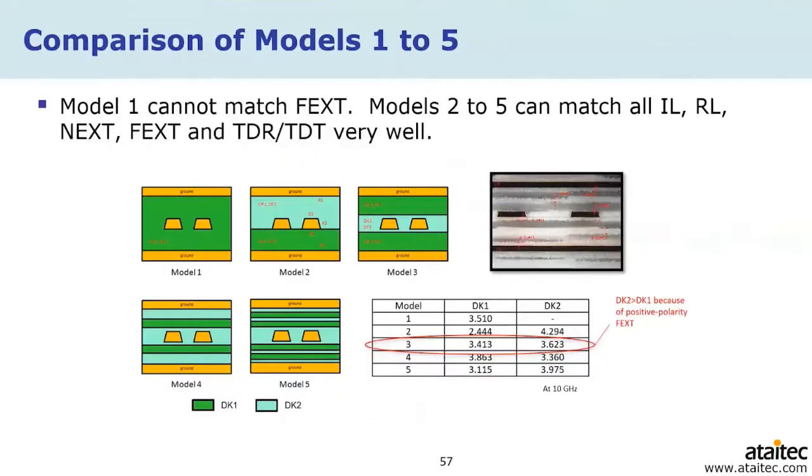So after we match so many terms, right, as parameters, TDR, TDT, then yeah, we can feel more comfortable about the Dk values we extract. And of course, the Dk values will depend on the model you choose. Right?